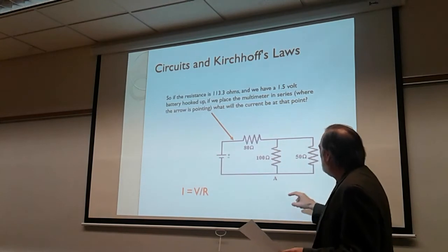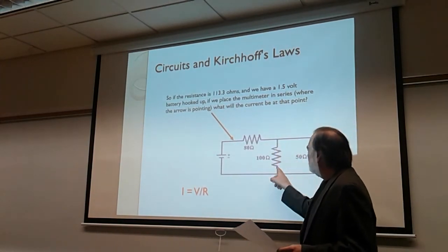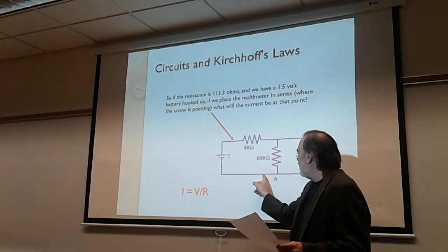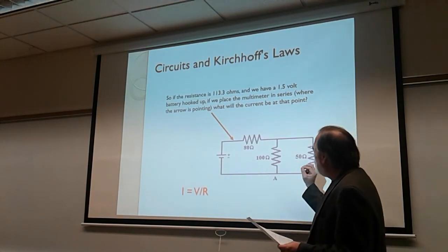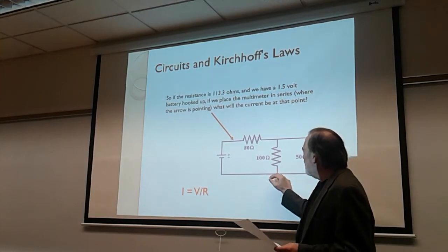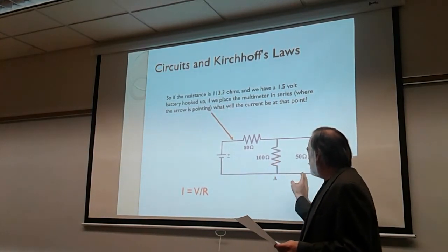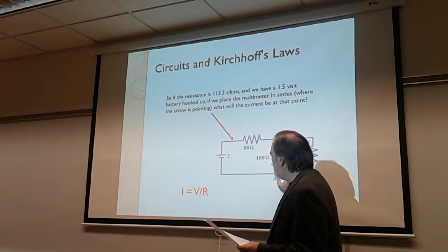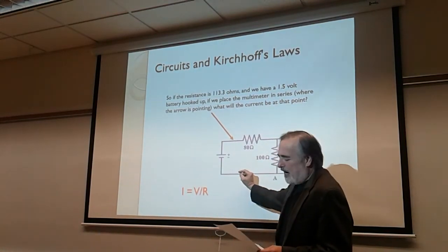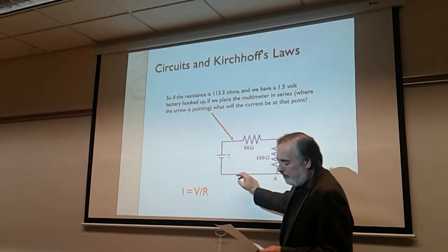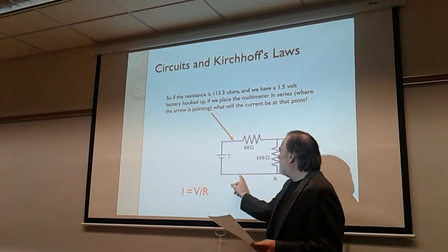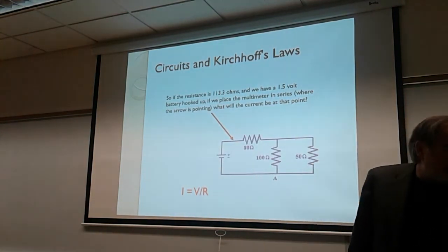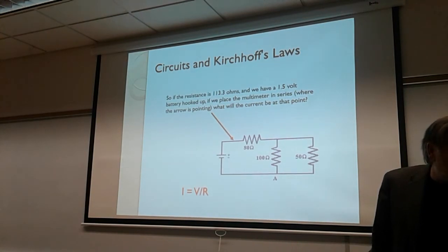Now, of course, these two will reduce the voltage because they're resisting. And what we end up with coming out of both of these, your calculation should show that we would reduce the voltage to 0 in this one and 0 in this one. Both of the currents, this one and this one, combining again. So at this point, what we would have is the combination of the two amperages, 4.44 milliamp and 8.88 milliamp, added together to give us the 13.2 milliamps that we started from, and 0 volts, which we should expect going into the opposite side of the battery. Again, I will give you this whole sheet as a JPEG in the Blackboard.